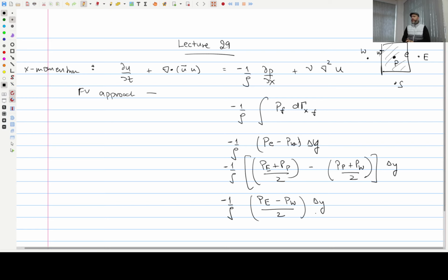Yes. So how can we define what should be the minimum size of the grid for this? Well, there is no thumb rule for the minimum size of the grid. The only thing is that if you want better accuracy, you refine the grid. There are many constraints, right? One is the computational power that you want to spend on it.